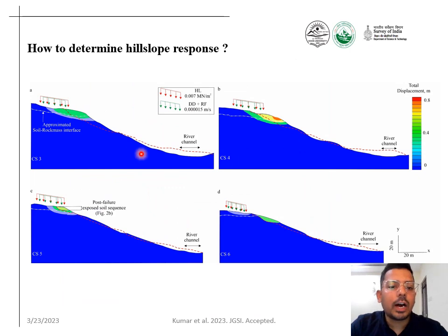And here you have the output. Different colors represent different grading of displacement. The blue represents the minimum displacement and the red the highest. So you will see in this part where you have human settlement, you have relatively high displacement at the top and lower at the slope bottom. So of course you will have a zone of detachment from here because the slope is steep.